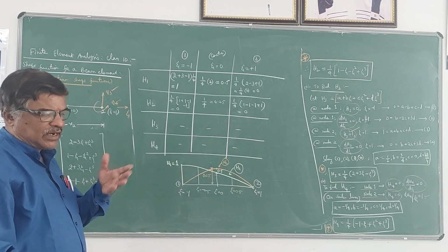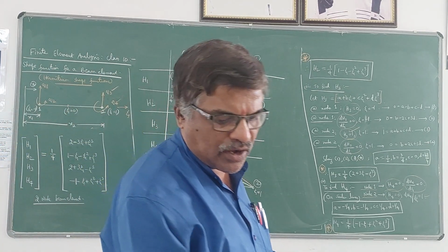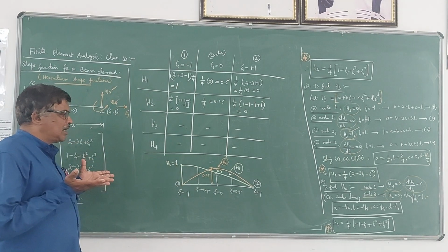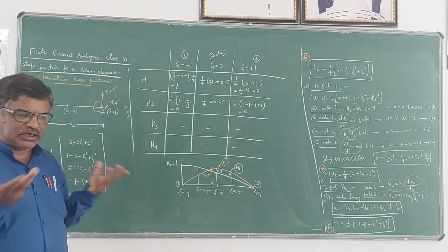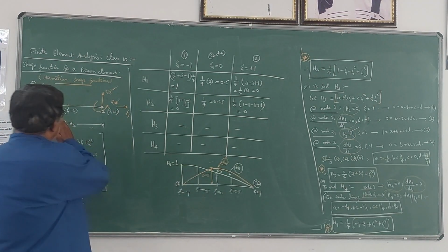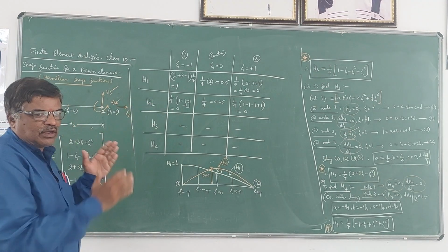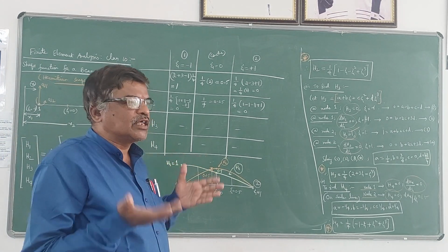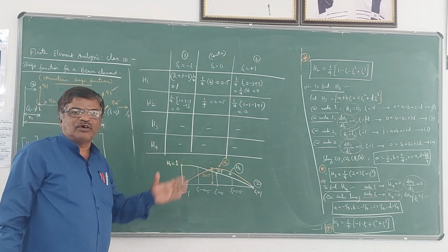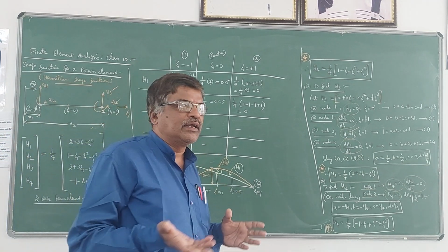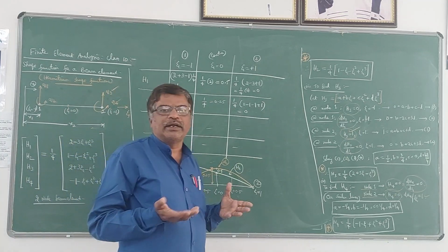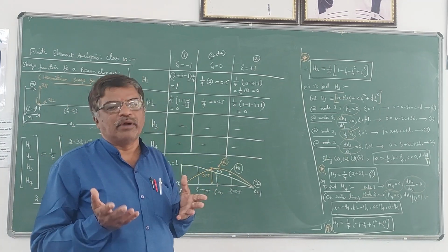So in general, all these shape functions give an idea how the displacement or the rotation takes place at different points along the length of a beam. By knowing the nodal displacements q1, q2, q3, q4, and by knowing the shape functions, you can always obtain the displacements and the rotations at any point along the element or on the element.